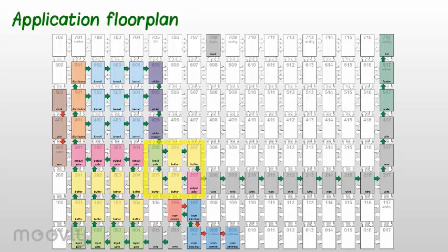The processed pixel values are temporarily stored in another set of buffers. The reason for implementing those video buffers is that in order to enlarge the resulting image on VGA screen, the application displays each bitmap line with 3 scan lines. Therefore, one buffer holds a line just being displayed, while the other buffer is being pre-filled with the next bitmap line. The output of those buffers is passed by wire nodes to the last module of the application, the VGA display module.